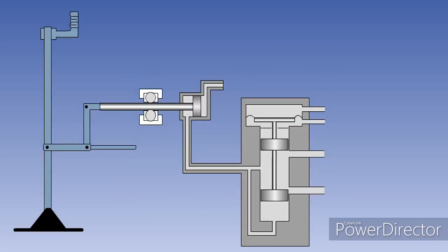Whilst the feel produced by a Q-pot is proportionally correct, its magnitude is quite small. To produce feel of a significant magnitude, the Q-pot would have to be very large. So Q-pots are normally used to control hydraulic pressure, which is used to amplify the feel up to a usable level.